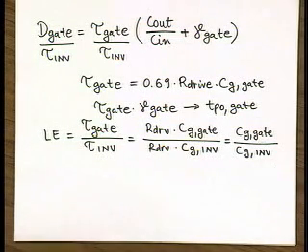Because by definition we adjust the size of a complex gate such that it has the same drive current as an inverter. So if you put the same load at the output, you will get the same delay. But that results in higher input capacitance because of the sizing of the gates.